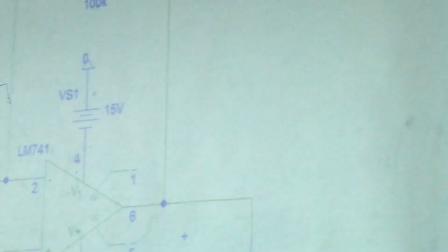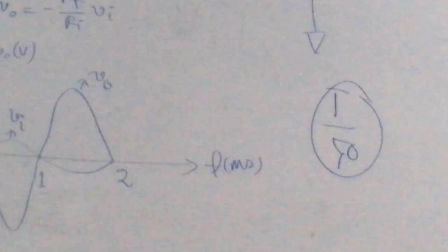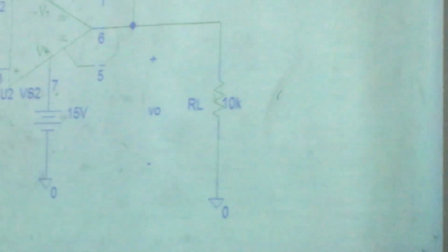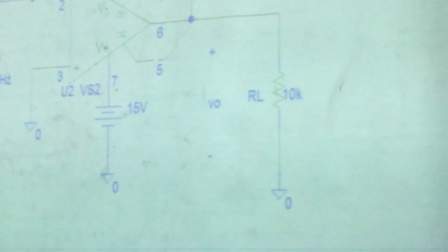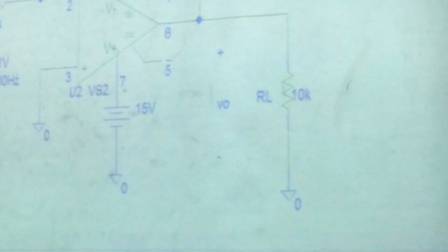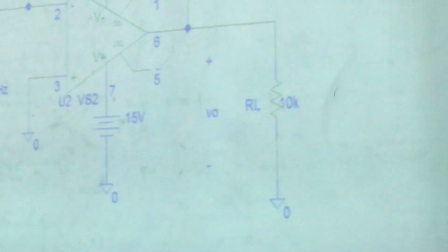Yeah? Step ceiling is going to be 0.04 milliseconds using t by 50. That rule, keep it in mind. You'll need it in future. Told you already, I'm going to show you many small items here, but you need to do it on your own later for other circuits or other experiments.